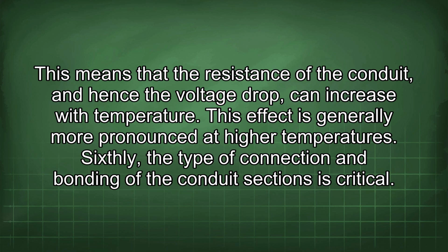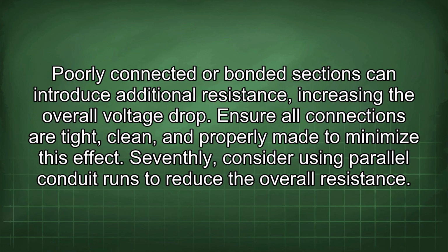Sixthly, the type of connection and bonding of the conduit sections is critical. Poorly connected or bonded sections can introduce additional resistance, increasing the overall voltage drop. Ensure all connections are tight, clean, and properly made to minimize this effect.